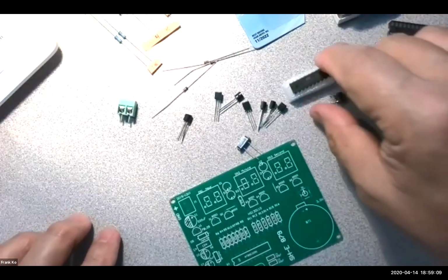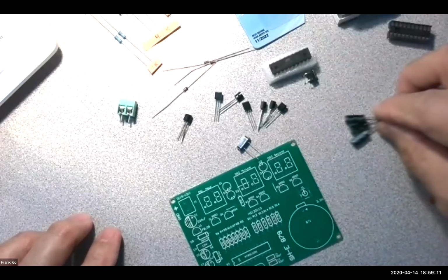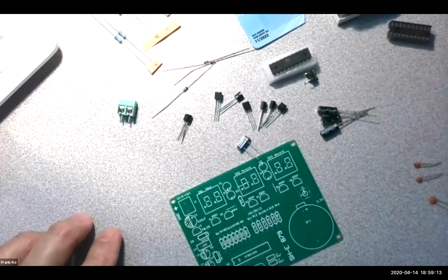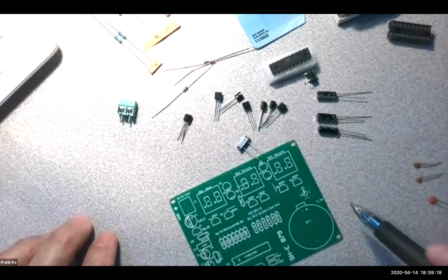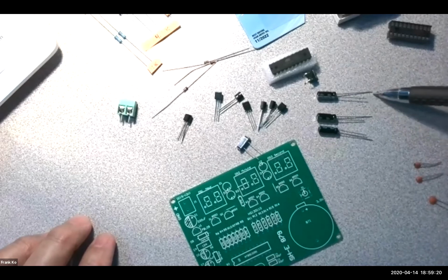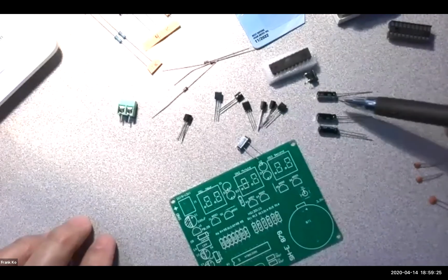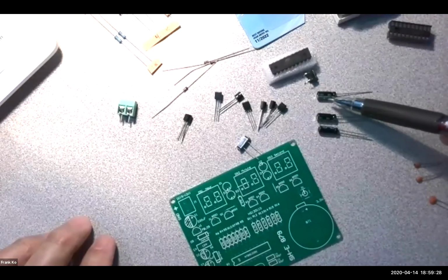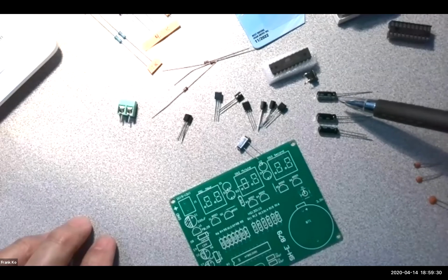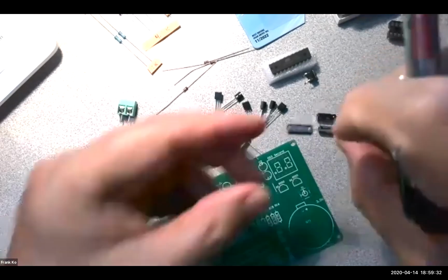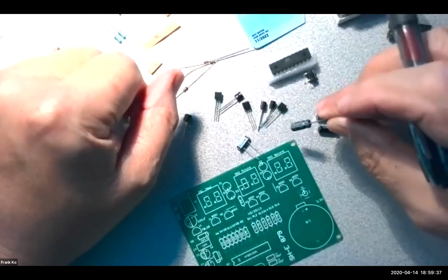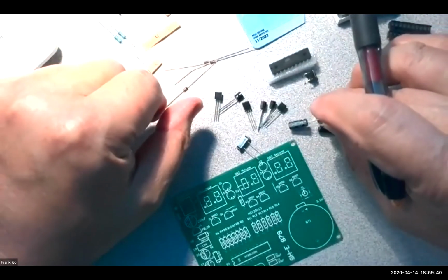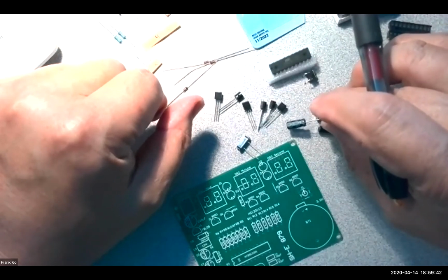Okay, moving right along. There happen to be 3 capacitors. These 3 capacitors are the same value. They happen to be electrolytic. So electrolytic means they're polarized, which means there happens to be a short lead and a long lead. Negative is short, positive is long. The negative lead is also identified by a white stripe on the side of the capacitor, and that white stripe goes to show a nice bar showing the negative symbol, that lead attached to that side is in fact negative.